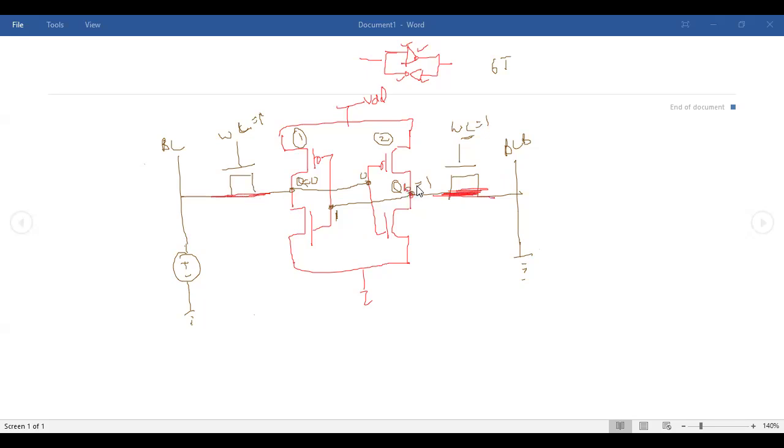Remember, QB equals 1 means this bit is at higher potential. When this is short, the current will move from high to low potential. So this 1 will become 0. When this 1 becomes 0, this 0 will get as input to here. When this inverter has the 0 input, it will give 1 output. So your 1 becomes 0 and 0 becomes 1.